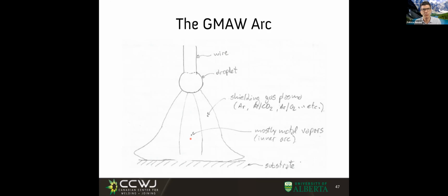So if you have more or less 1% manganese in your electrode, the fumes can be up to 50% manganese. That's a lot, right? So these things we're discussing here are topics of super high interest for the companies making machines and electrodes, because reducing manganese is essential.